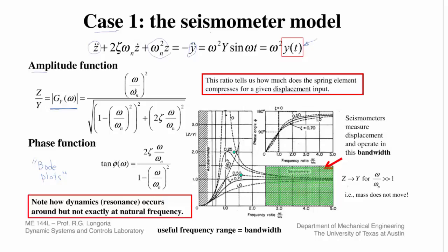I've defined and put in my definition of my natural frequency, which, remember, natural frequency for this system is the square root of k over m. So note that in order to understand the amplitude ratio here, output over input, all you need to know is the natural frequency, the undamped natural frequency. Remember, there's differences, and I'll show you that in a second, from the damped natural frequency.